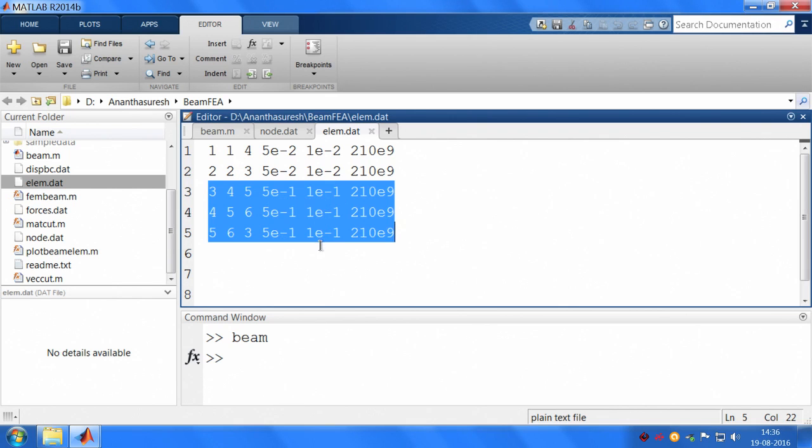This is how we can make rigid blocks in finite element analysis using beam elements. We make their cross sections much larger. If you want, you can make Young's modulus very large, whichever. What matters is E times I, Young's modulus times the second moment of area. So, you can make either of them or even both of them very large compared to the flexible segments. So, you can create a rigid block.